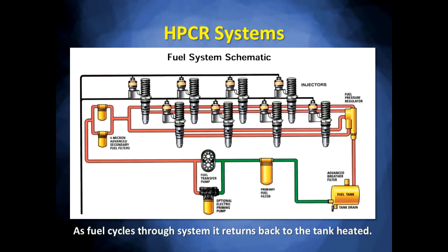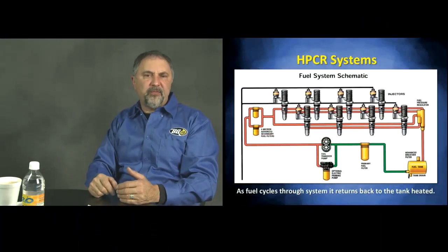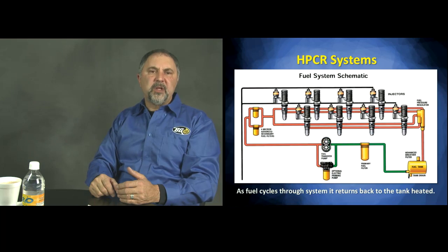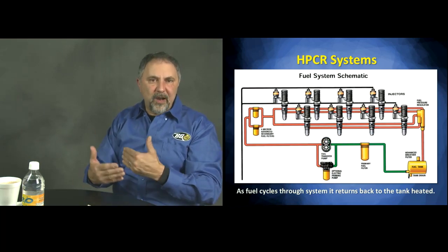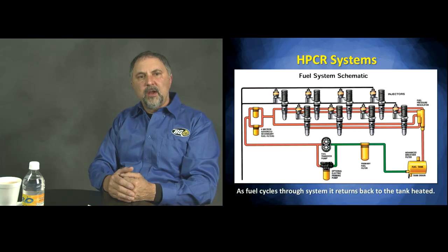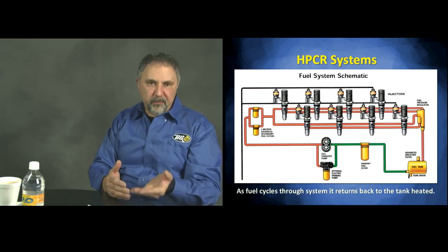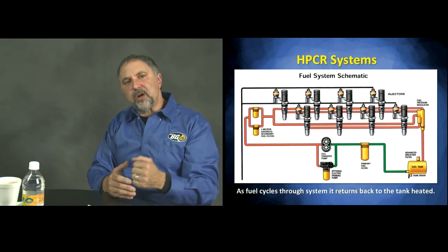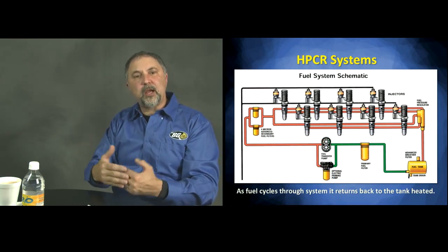And what's going on with these modern diesel engines is they're becoming more like gasoline engines, where you're looking at common rail systems where you pull the fuel from the lower right fuel tank and through your fuel filter and fuel pump. It's sent up to the injectors, and when the injectors turn on, it sprays fuel into the cylinders. Now, gasoline engines always had a pressure regulator that recirculated fuel back to the fuel tank. Diesel engines that came up recently, they call it a common rail system, high pressure common rail system. And high pressures are heating the fuel up, because you raise the pressure, you raise the temperature. Now, these high pressure common rail systems are returning the fuels back to the tank superheated.